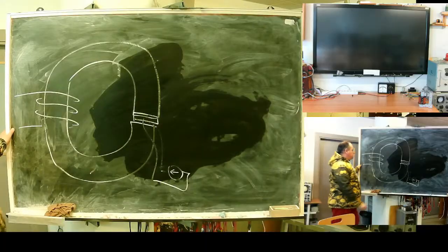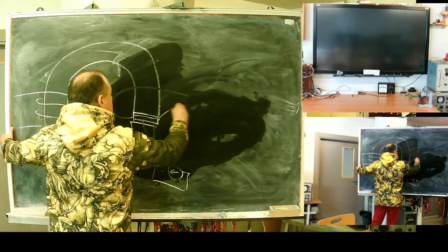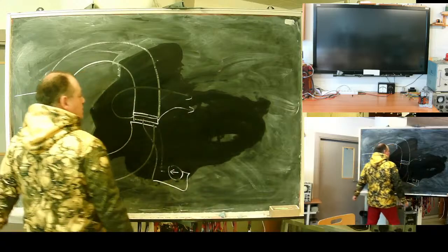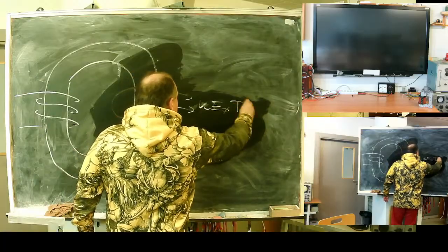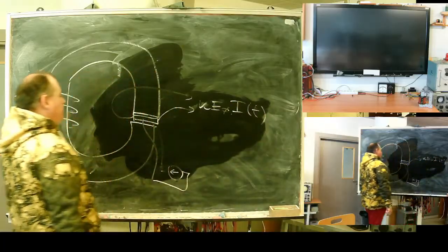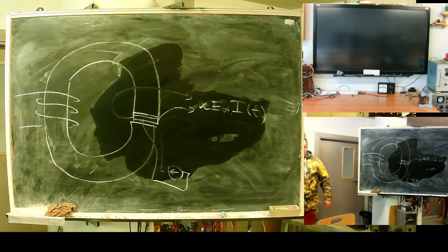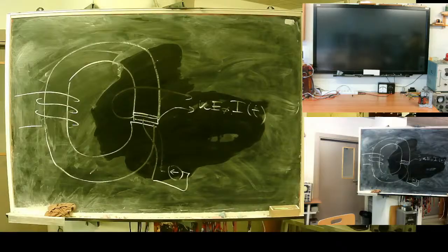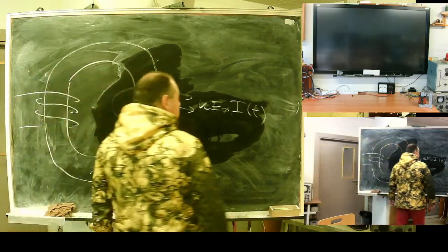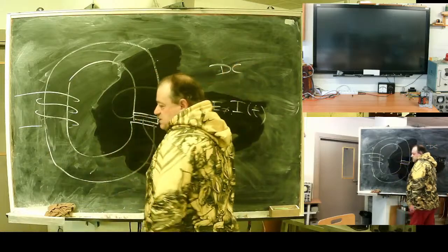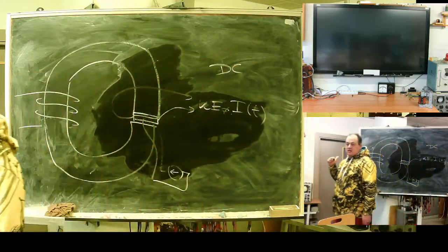Put a zero source, and you will get, in theory, E0 proportional to current as a function of time. Looks very nice, including one important thing. Hall sensors can operate in DC mode. When you need DC measurement, a Hall sensor can be your choice. They operate starting from zero.